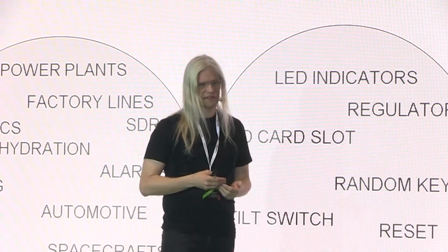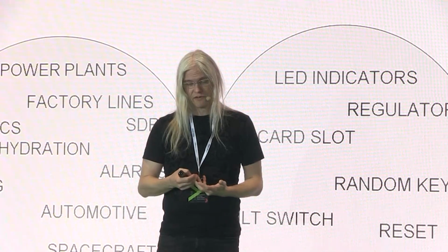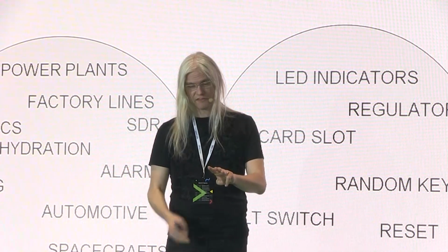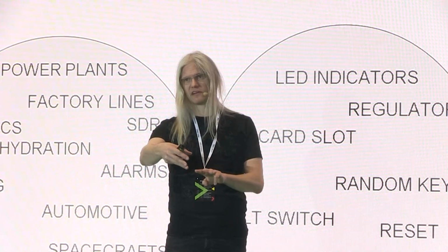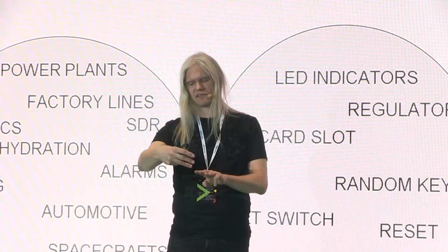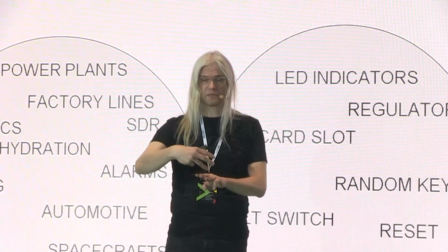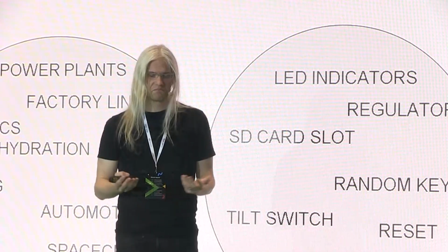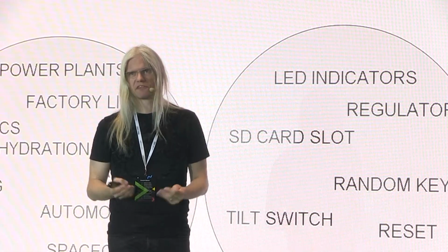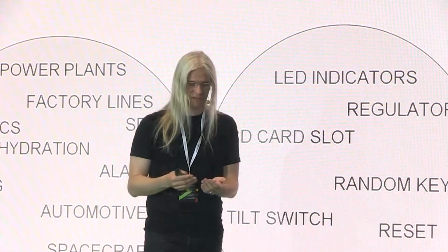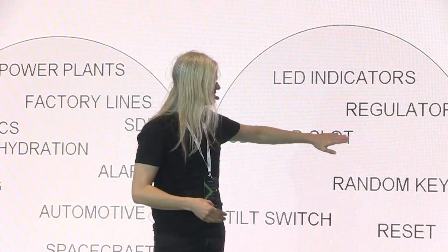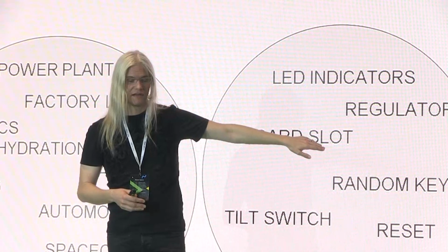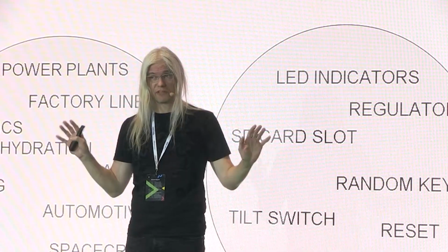And since we support SPI over GPIO, we can just take some pins on our system and turn them into an SPI bus, that means that we can solder them into an SD card or MMC card. And that means there's a very simple way, if you have a BeagleBone or whatever, to get a full gigabyte of storage, several gigabytes, terabytes, just by soldering free lines, instantiating a bitbang GPIO driver, and then running SPI on that. It's not going to be fast, but it's going to be big.